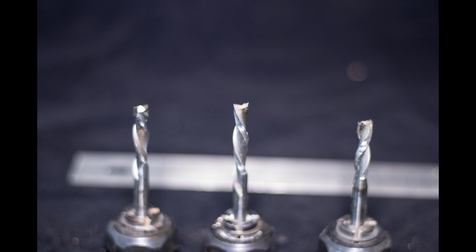They all serve a very specific purpose, so I invite you to the manufacturer's websites to read up on the bits and understand what each does, when you use the up, when you use the down, when you use the up-down. I personally like the up-down the best. Seems to be a cleaner cut, especially when you're cutting plywoods and laminates. Does a very, very good job, leaves very little chip out. A very good bit. So certainly a must in anybody's CNC tool database, the 1/4-inch end mill.